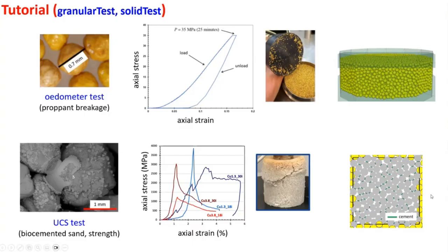There's all kinds of stuff that we were able to investigate here, because this material, as you can see, is not perfectly cemented. There's a number of grains, like here, where the cement didn't even form. And these little crystals, if you will, that's actually the cement as well. A lot of the calcium carbonate just precipitates on the surfaces, which means it's not really helping in making it stronger.